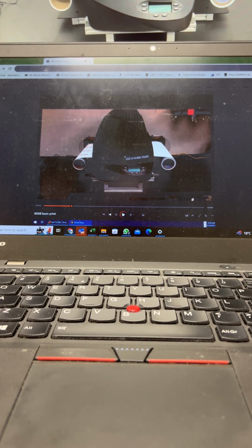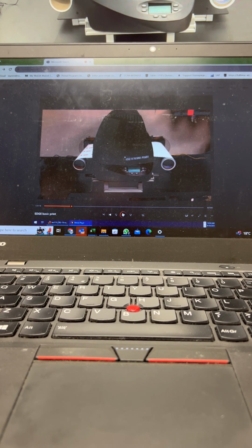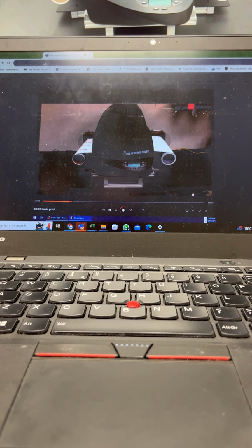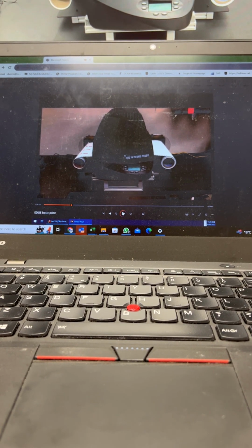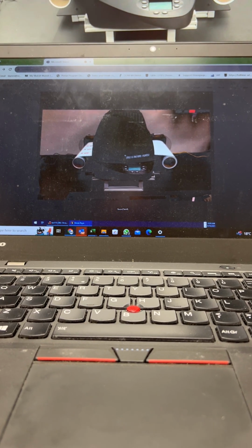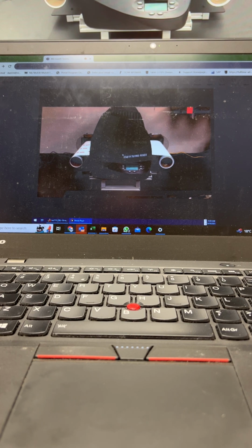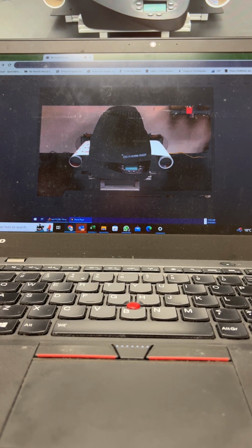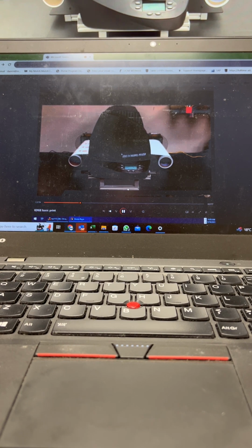So generally tell customers to use a Swiffer duster or rag to clean off their area and have the vinyl fall out smoothly across their table rather than curling up on top of it and dragging across. Once the Edge prints the first color, if it's a multicolor job, it'll then automatically rewind the vinyl, and then it'll ask you for the second color, which I think this video actually does.